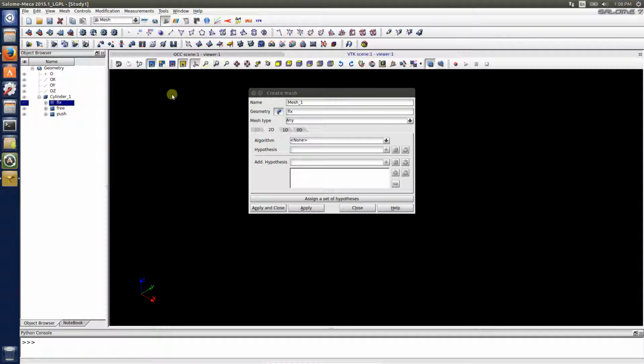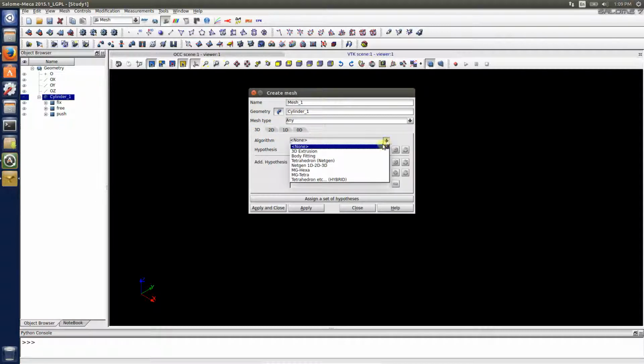You'll notice it moves directly to the 2D. So you really want to make sure the body or the solid that you're working off of is the one you click. And then it basically says you're back in 3D. Here, the most successful I've found is the one that says NetGen 1D, 2D, 3D. That's the one I found that behaves the best.